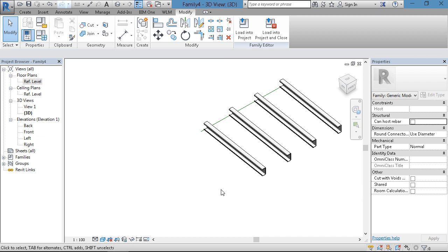So, you copy that, Control C, and then put your formula here, directly on the Length. This one, length. What is written here should be the same. So, that is big L, E, divide, slash, Control V. And then you have 4 purlins. So, 3.